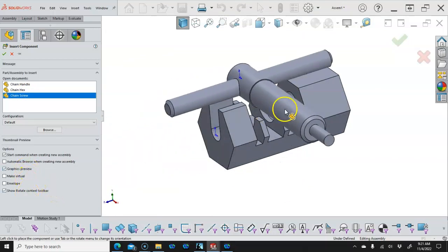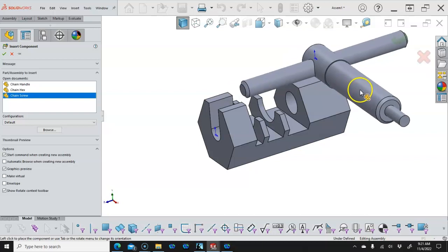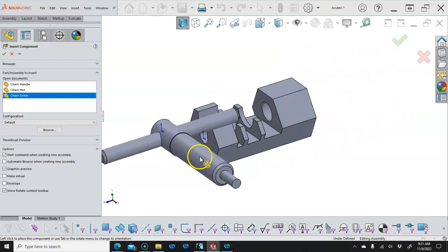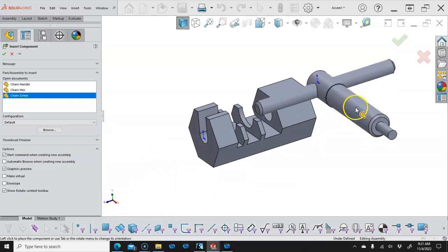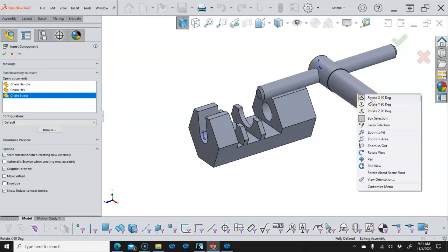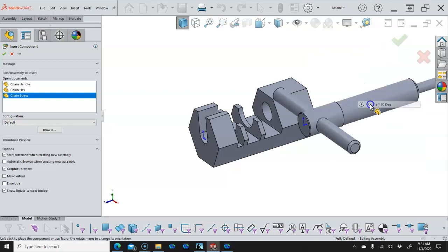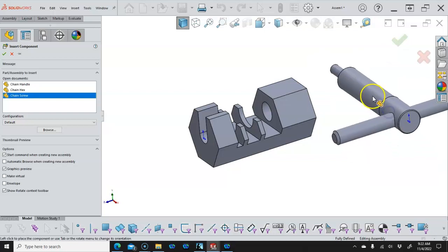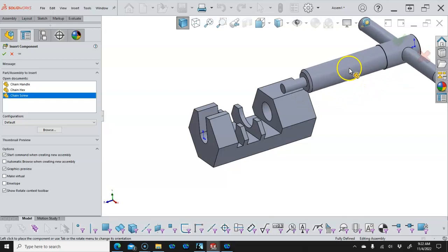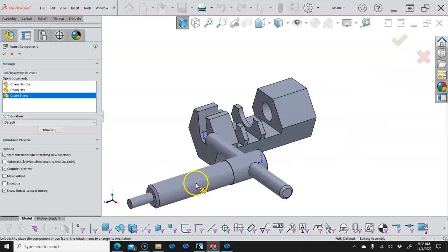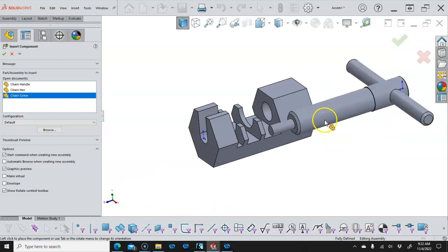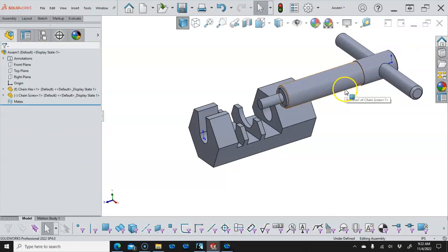Let's see, the rotate context should be showing up somewhere, but not seeing it. If you have the little box, then we would rotate about Y. And oh, I'm still looking at it for 2021 apparently, so got to remember to start hitting the right mouse button to rotate around Y. All right, so that gets us a little better into position. So prior to 2022, little box would pop up with the angle and the direction of the rotation, and we just select out of it.